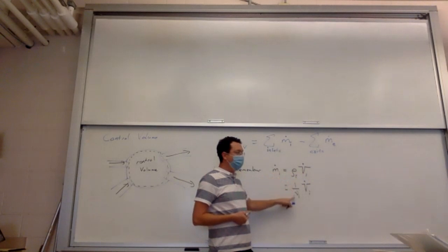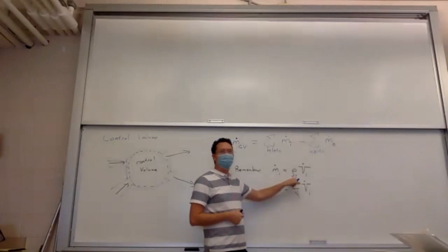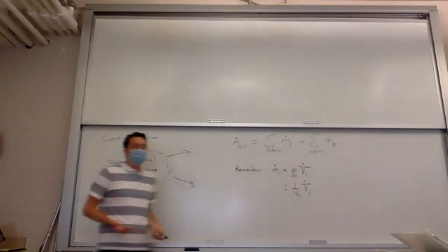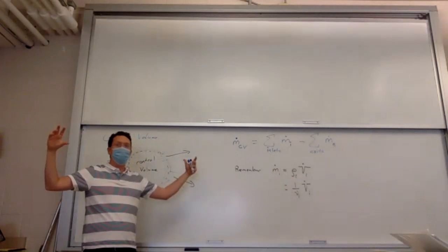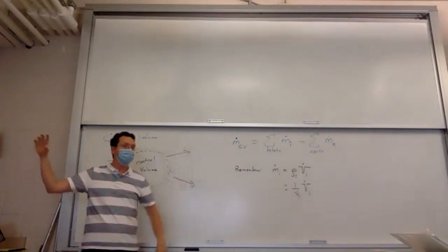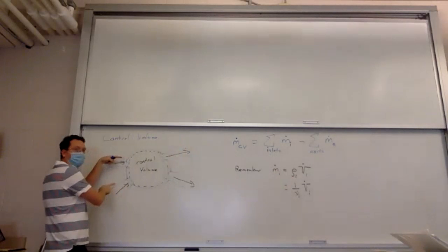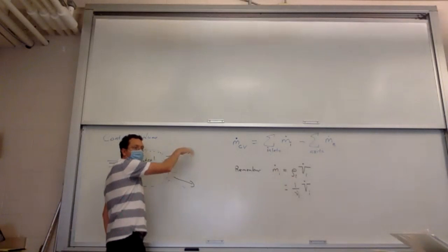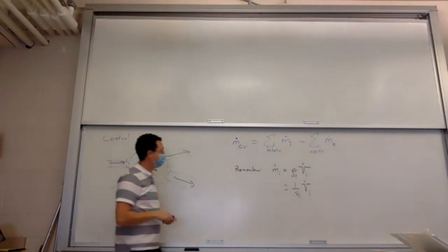Density here. Now, when we did Bernoulli's equation way back, densities were constant throughout, so you just have one number. Now, however, we're not going to just have a simple pipe. Now we're going to contemplate a mixing chamber. You take liquid water, mix it with steam, right? So on one input, you might have one density. On another one, you might have another density. And if you know the temperature and pressure when it leaves, you'd have a third density. So you have to account for that.